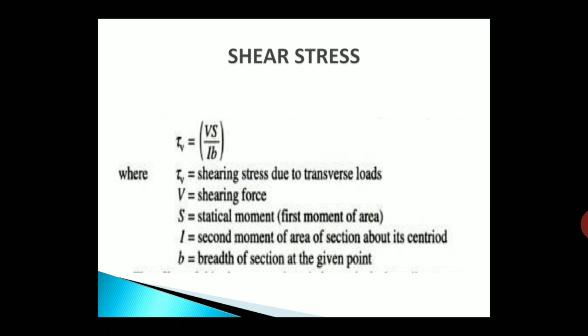But in case of PSC beams, we have the relationship tau V equal to V into S divided by I into B, where tau V is the shearing stress due to the loads, V is the total shearing force, S is the statical moment or first moment of area, which is nothing but A into Y bar,